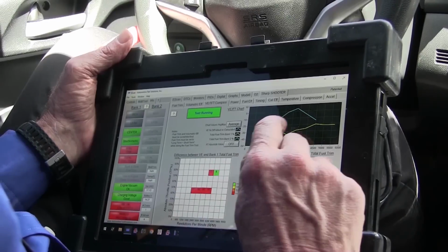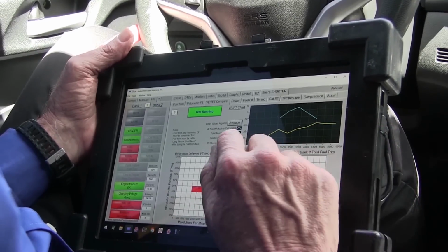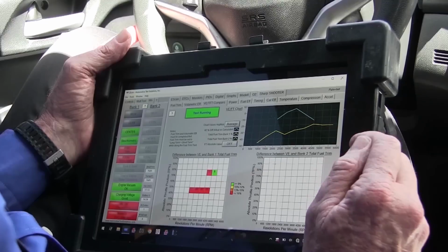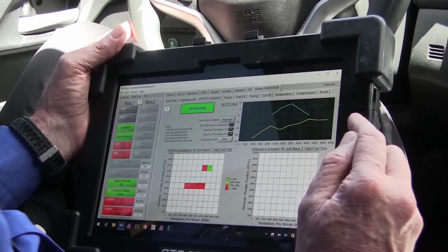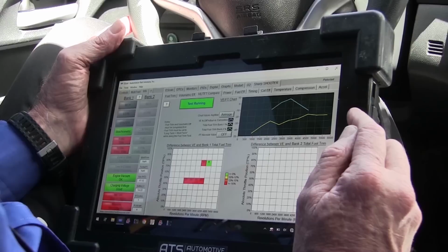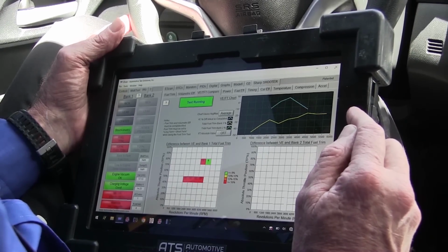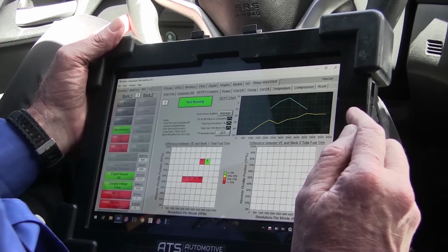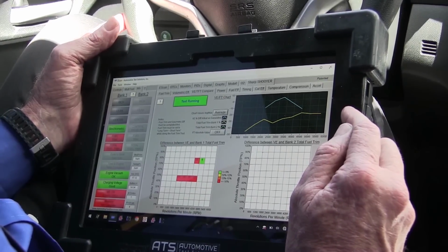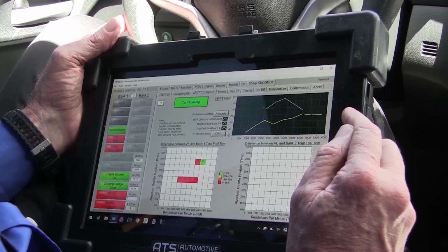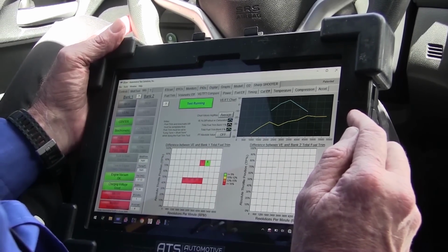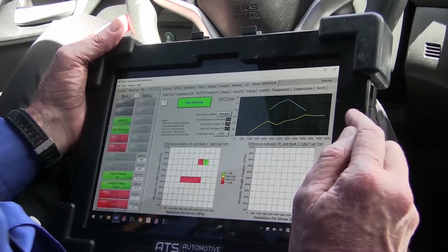But by the way this trim is laying out, whenever I've seen injectors, it's always linear, and that's not linear. So I don't think that can be the injectors. And I don't think that's the fuel either. Now, the shop that this is at, he told me that this car came in on empty and he put fuel in it. So he said it had the problem when he drove it over to the gas station, and when he filled it, it still had the problem. So the fuel has already been changed. So I'm not going to test the fuel because I don't think that's where my problem is.